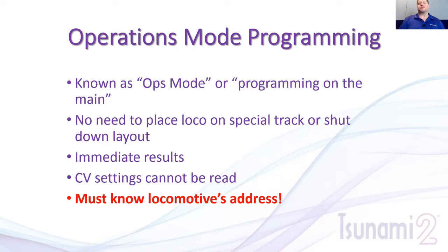So you'll instantly hear it. Same thing with volume controls. You'll hear that change. Hey all locomotives, listen up, locomotive 1000, change CV128 to a value of 100. And so it's going to reduce the volume. You'll instantly hear those changes.